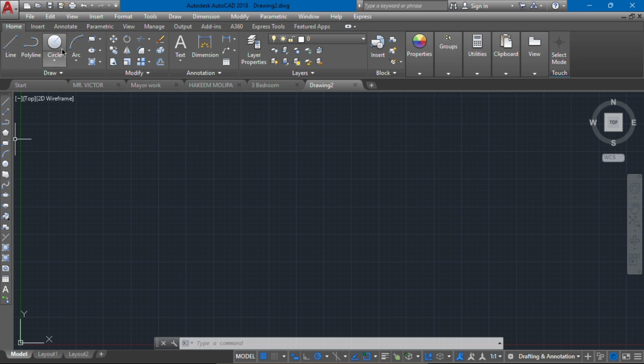So now, these are our drawing tools, which are now shown here. We are now having our polygon tool, which is in the same place as this, but it's showing rectangle here, which is this rectangle. For you to get this polygon shape, you click on this drop down arrow. We are having the rectangle and the polygon, which are now separated outside here for easy access. You can just come here and select them easily. Here we are having our ellipse, center axis end, and elliptical arc. But here we are having only ellipse here. I think here is also ellipse arc. Okay, this one is ellipse arc, but this is the ellipse. So if you need to draw various forms of ellipse, then you can just come here.